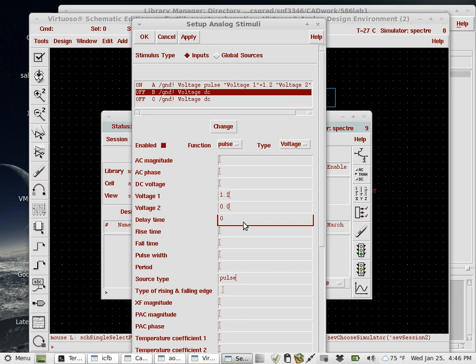Yes. So I have a question. Can't we remove the buffers and just use the inverter, and make this as real as possible? Yeah, you can. This is why we have rise time and fall time, to make it realistic. We can specify that and just remove it. Sure, but the problem with this is the supply voltage can supply unlimited current. But the driving capability of an inverter is limited, which is more similar to a real situation.